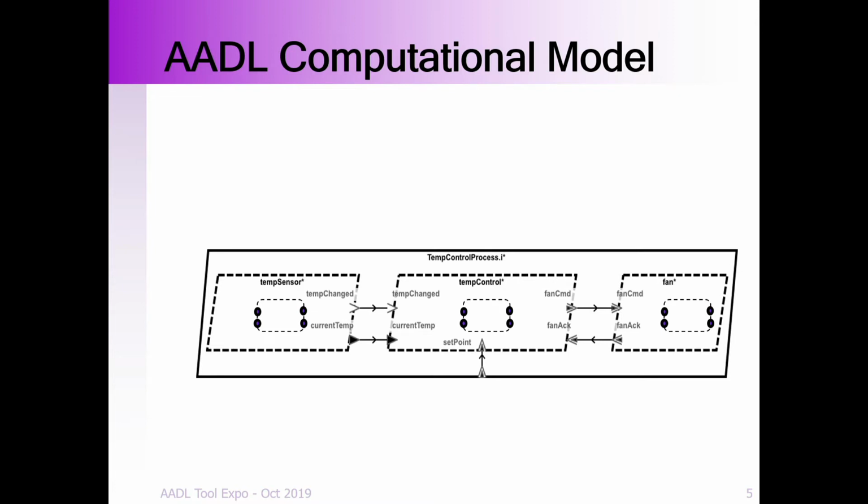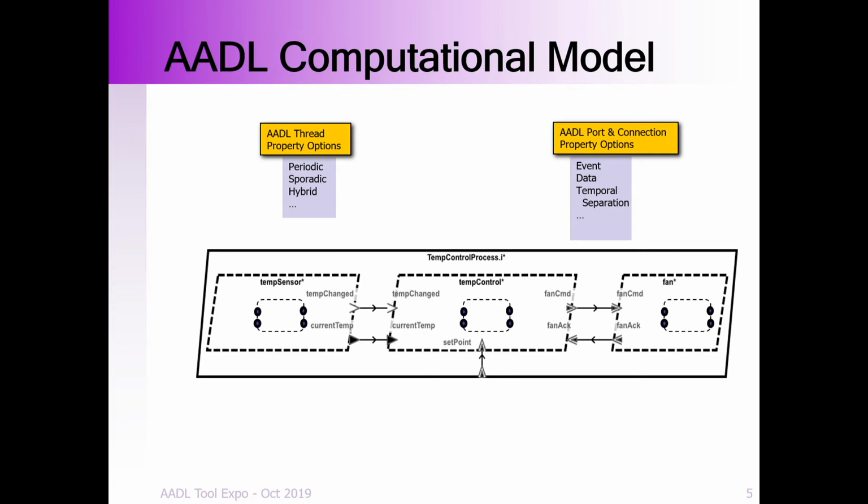So one of the things that's been emphasized throughout the day is that AADL isn't just boxes and lines, right? There's some notion of semantics associated with it. So what does that mean? Well, AADL provides this sort of semantic palette or collection of computational patterns that you would often see in real-time embedded systems. So there's a collection of patterns for threading, whether your threads are time triggered, event triggered.